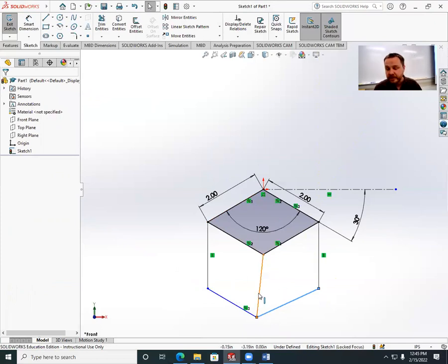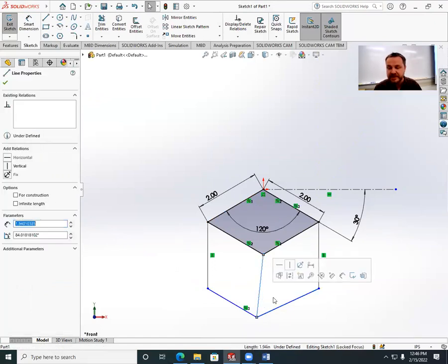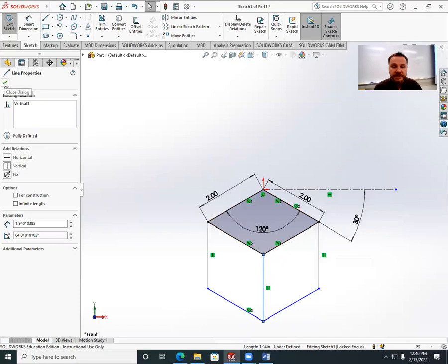So this line right here, see how these two are vertical? I'd like this one to be vertical. So I can just click on this line here and specify that this should be vertical. And that forces it to be vertical. And these lines over here, probably just by definition, are going to end up parallel with these others. Done with this line here.